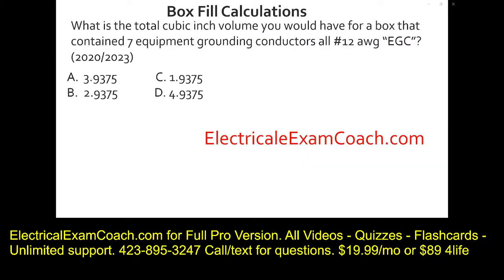What is the total cubic inch volume you would have for a box that contained 7 equipment grounding conductors, all of the 12-gauge persuasion in the 2020 and the 2023? I left out all other conductors because you're going to use the same rules in that after you do this calculation, you group it with whatever the largest conductor is in the box, like you learned previously.